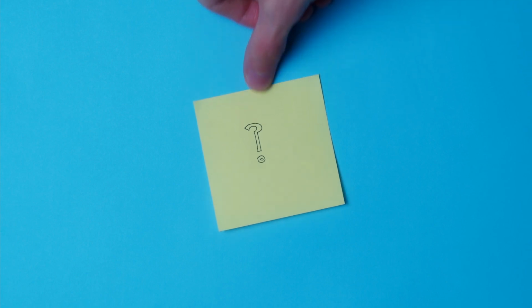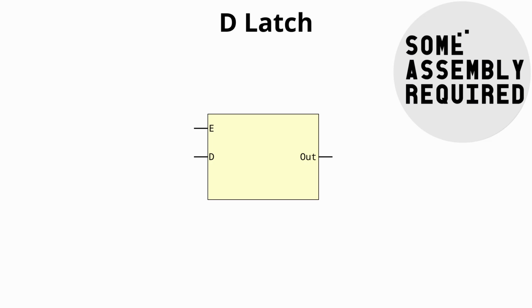I mean, if we're only interested in a short while after the transition, shouldn't we just make sure that that's when we're enabled? The answer is that for flip-flops, this input isn't called enable. In fact, a typical flip-flop will actually also have an input called enable, which will behave precisely as it does with the latch. But this input, the one that triggers latching the data input only during the transition, has a different name. It's called a clock. On the schematics, it's indicated by a small triangle inside the flip-flop's body.